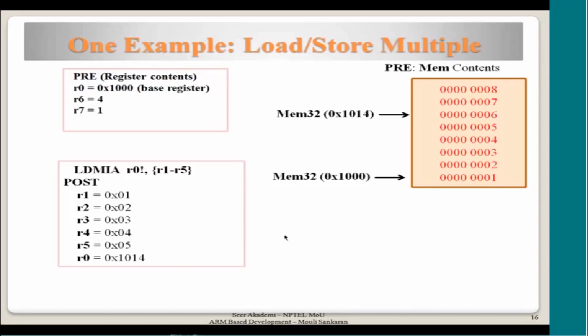So please remember, when you have multiple registers to access, the address has to be modified. Otherwise, you will be accessing the same address, you will not change anything, right? You will be overwriting the same location. So if you are accessing multiple values, you have to increase or decrease the address so that you access different values every time. So that is implicit.